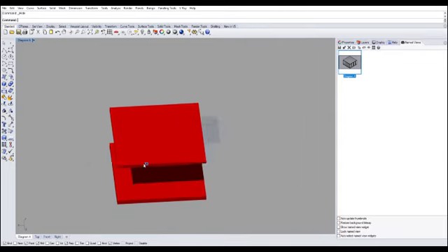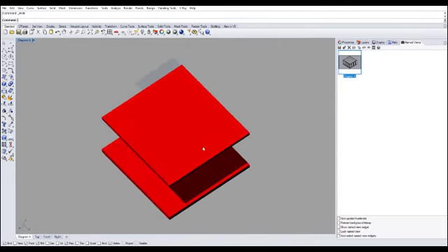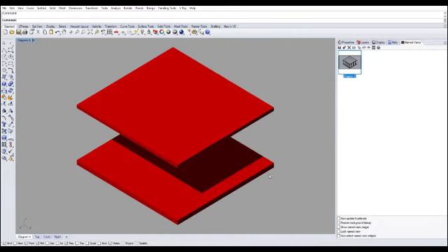Now we're not going to render just yet, right? Because we're going to systematically control and be consistent with all of our views, which is our diagram A view. Now this is ready to render. So let's render this. Where's my render option? Which is this. Here we go. And to render, we're going to click on this, called Render with V-Ray.